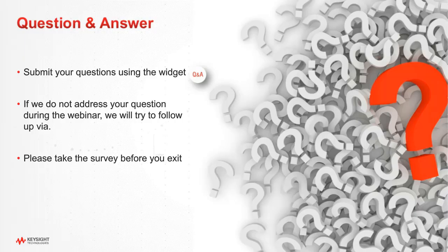Within the working group, there is a set of proposed test fixtures that we are working towards, but the USB-IF will need to announce the test fixtures. So that's the first part of this first question. And the second part of the answer is, in USB 3, there's no notion of a controller. So in addition to the test fixture, there'll also be something called a USB 4 controller. And its job in life is to put the product into these test modes.